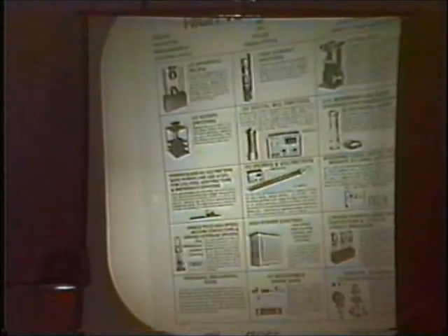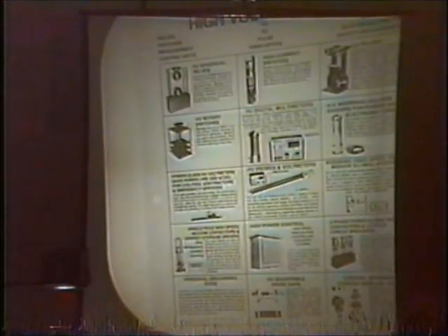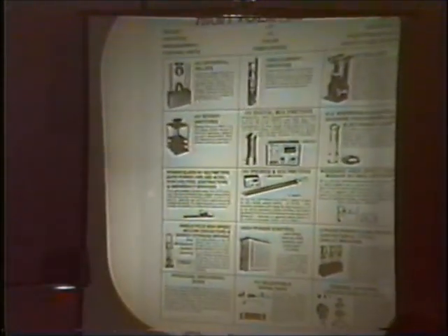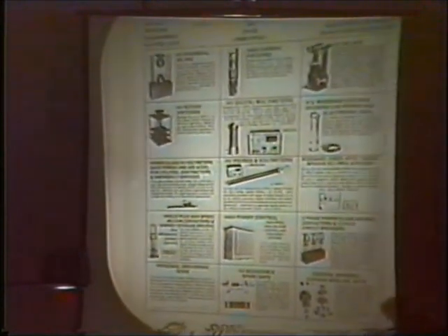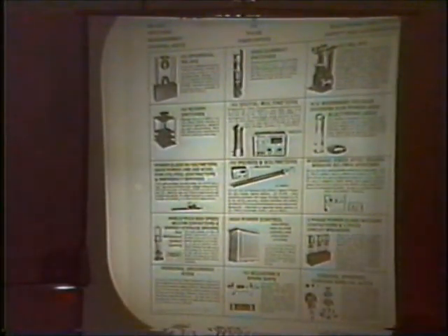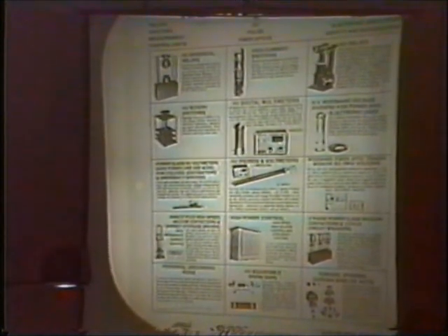Okay, these are some of the other devices. Your off and on switches for high voltages, and those toroids that you see down in the lower corner there come up in sizes up to 52 inches in diameter. Basically what they are, they're a capacitance end that you put on the busy end of your Tesla coil to keep it from sparking unless you really want it to. It's a capacitance device which you load, and it helps you control your Tesla coil and the voltage that's on it.